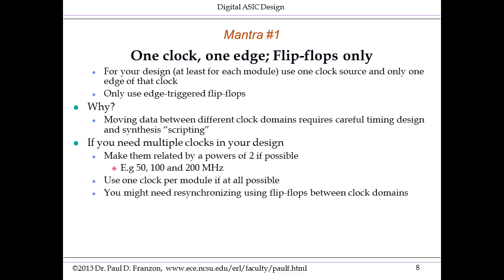Okay, the first mantra. Say after me: one clock, one edge, flip-flops only. Say it again. I can't hear you. Seriously, why am I asking this? You will find your life with synthesis a lot easier if you follow this rule. I strongly recommend that at least for each module, you have one clock source and only use one edge of that clock. And for your entire design, only use edge-triggered flip-flops.